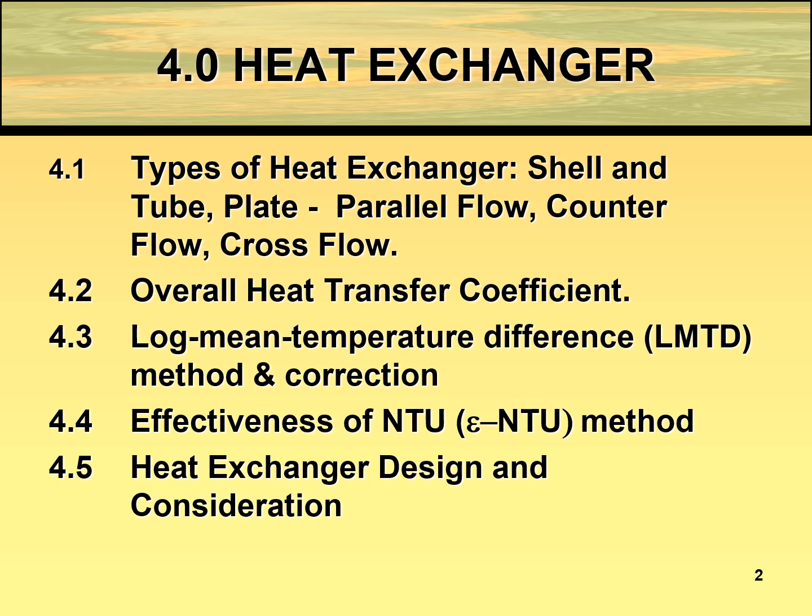So there are 5 subsections for this chapter. First, we're going to look at the types of heat exchanger, and then the overall heat transfer coefficient, which is the derivation from the heat transfer processes, and then the principle of the log mean temperature difference method, or LMTD method, which is applicable for concentric tube.